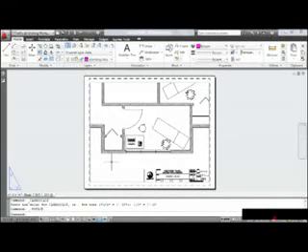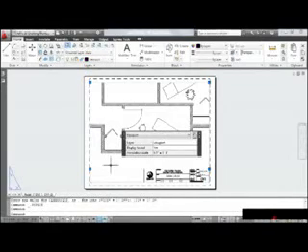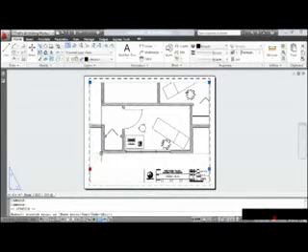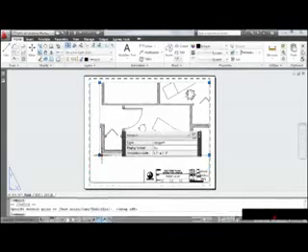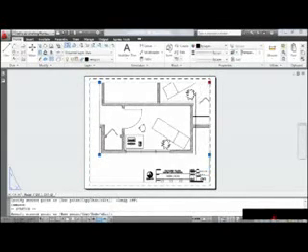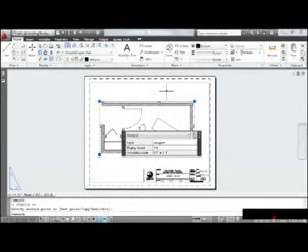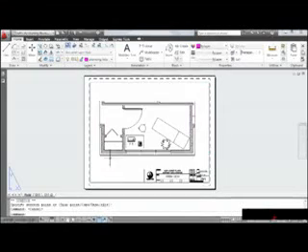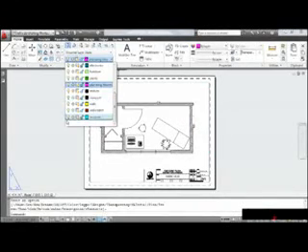Remember that a viewport is a window into model space. Watch this. If I select the viewport boundary, I can adjust its size using these grips. I'll click this grip, and I'll pull it up to here. Now, I'm being mindful of my running object snaps. In fact, I'm going to turn those off momentarily. I'll pull the viewport corner up to here, and then I'll grab this corner, and I'll pull it down to here. When I'm finished, I'll press Escape. By adjusting my viewport boundary, I was able to focus on exactly the geometry that I wanted to see. Let's turn the viewport layer back off.